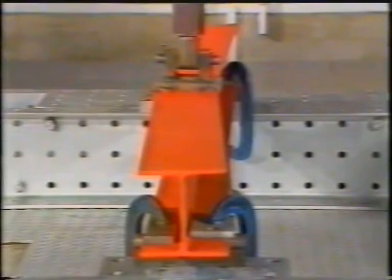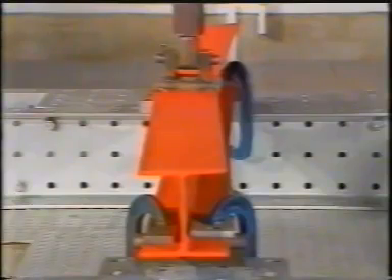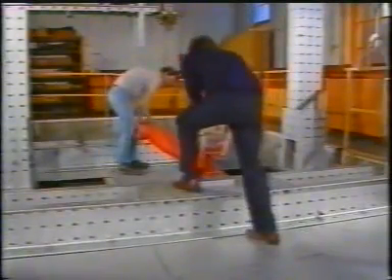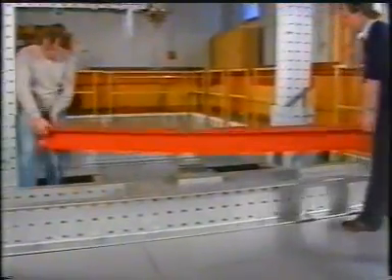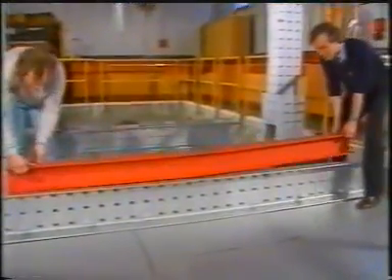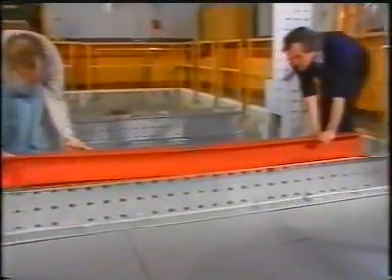It can be seen that lateral deformation and twisting occur, together with plasticity. Removal of the load is accompanied by only partial recovery of deflection, and significant permanent bending remains in both principal planes.